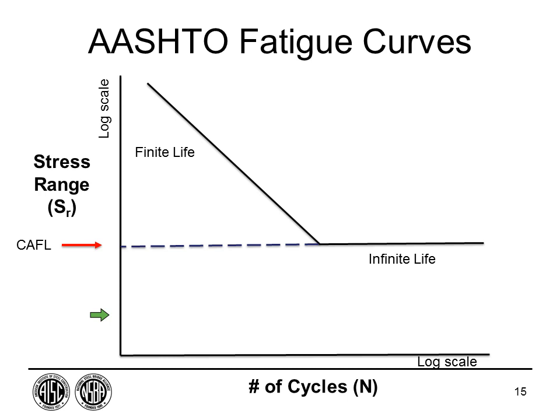Sometimes you have to put a temporary bridge in, right? It's going to be there for a certain amount of time. Well, maybe in that case you would design for finite life because it's not going to be there for more than 3 years. But generally speaking, I would encourage folks to design for infinite life. And it's generally easily attainable.